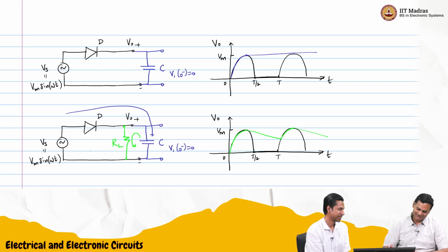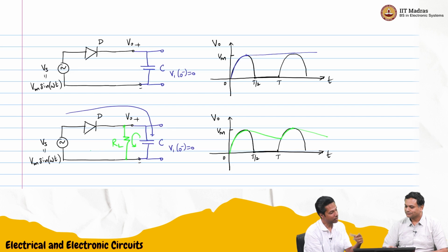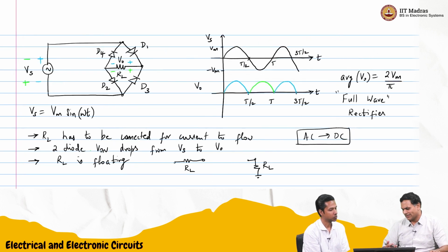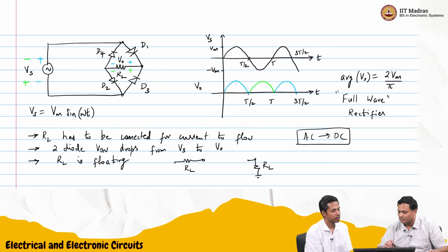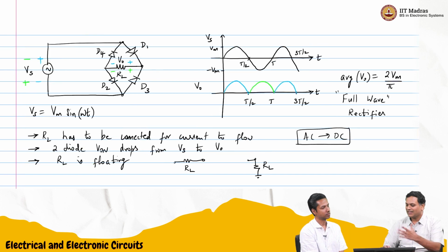So that means if you put the same kind of capacitor in the full wave rectifier, it may even work better, because we have this double ripple. If you put a capacitor across RL, it may work even better. We'll let the students think about what will happen. There may be better filters and better rectifiers also. But this is a good starting point.